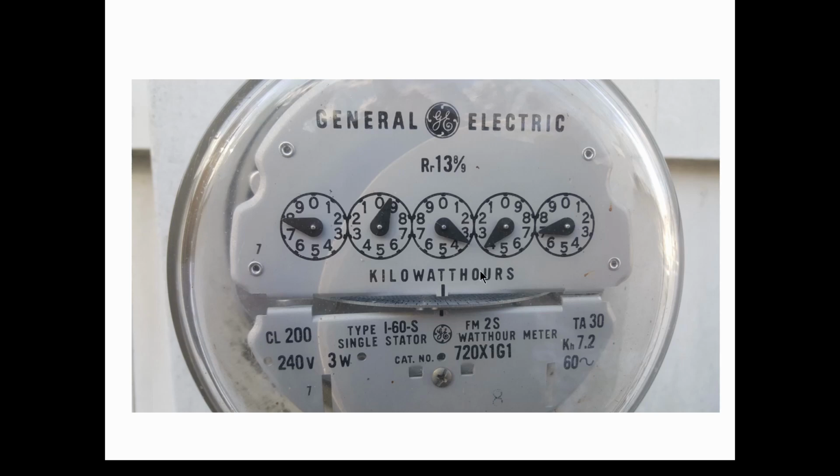Thousands of watt hours. And this older mechanical meter has these 5 dials. And it is constantly measuring 24 hours a day how much energy, how many kilowatt hours are being used by your home or your apartment, okay? And if you know how to read this, you can at any point in time figure out how much energy or how much power has been used by your house. And you can measure it every hour, or you can measure it now and then come back in a day and measure it and see how much has been used in 24 hours. You can measure it once a month.